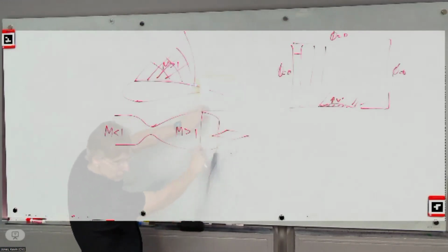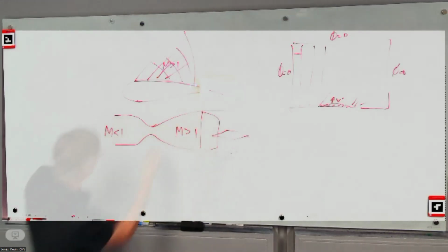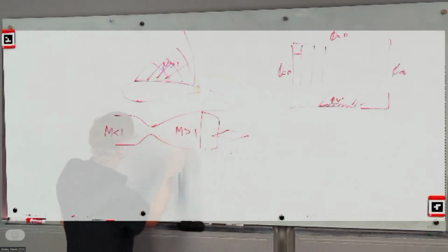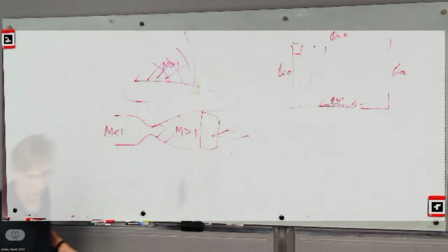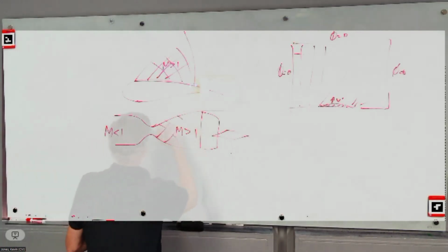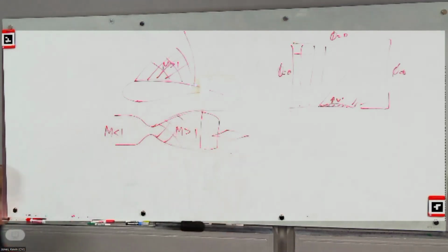Boundary layers for sure, but do you have some messy distribution of Mach across there? So I think they used the method of characteristics in here to shape this in order to get as uniform a Mach number as they could. It turns out the shape of this affects that distribution. Anyway, I think that's about all he has in his higher order schemes.